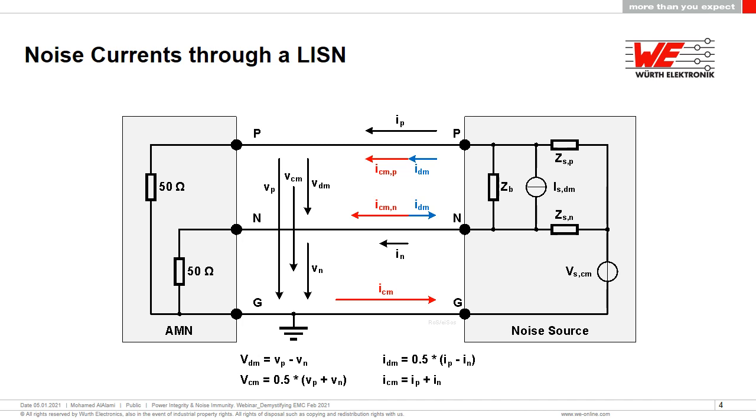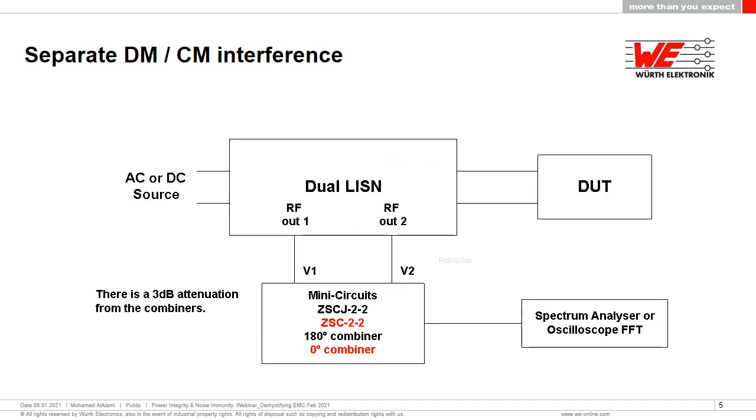And identifying where those loops are, identifying where those parasitic components are that provide the pathway for those high frequency noise currents to flow through, that's also the other challenge in order to identify where you need to introduce your solutions or minimize those loops from a layout tracking point of view as well. So cut a long story short, with LISNs, when you come to test, you're looking at both common and differential combined together. So one of the purposes of today is to make life a little easier by introducing this.